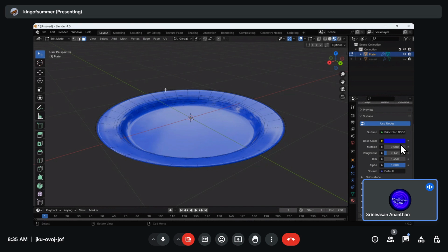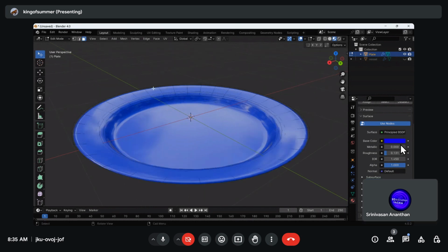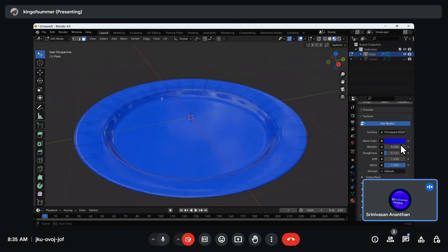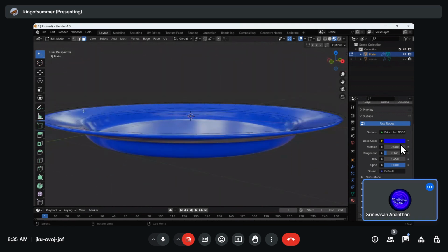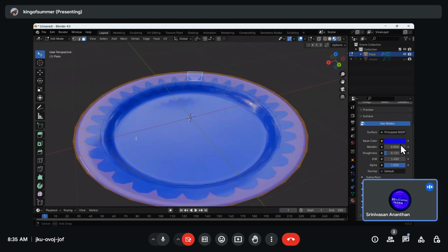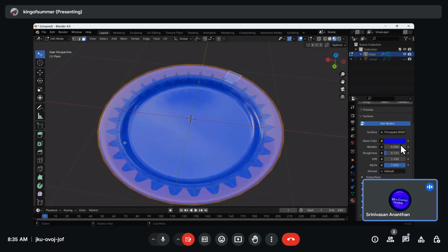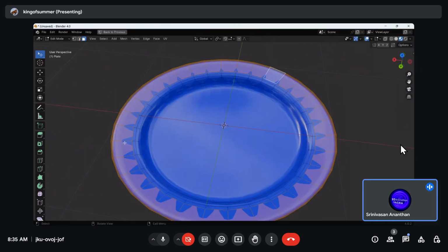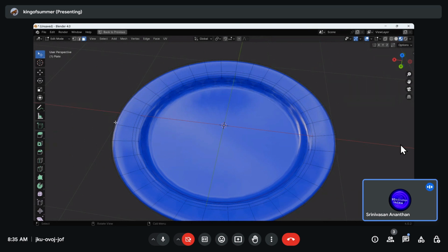Inside that, one face is there. Slowly move your cursor. Bring the camera up a little, like this. Don't change the view. Ctrl Space. Now Alt A. Next to what you have selected, one more thin face loop is there, inside. Select that edge loop.